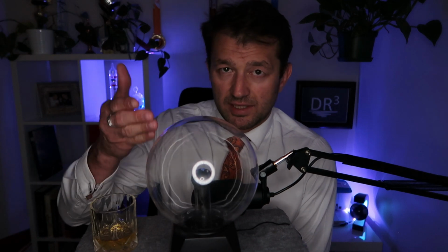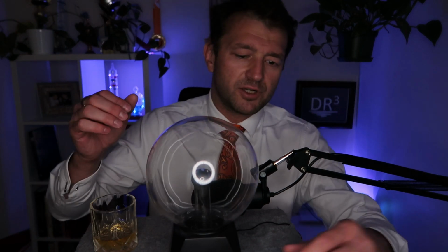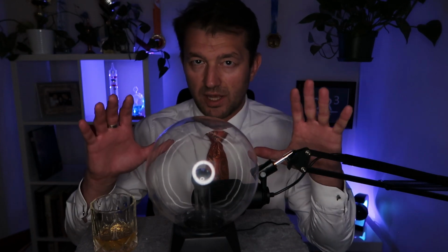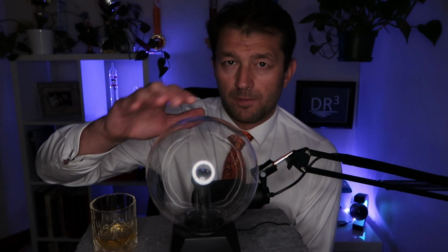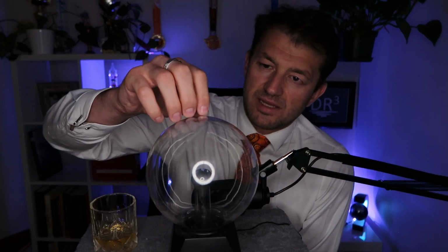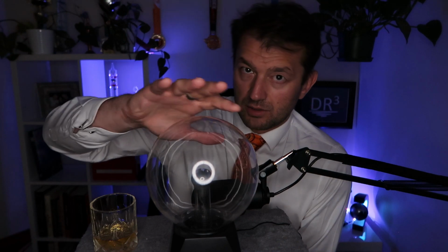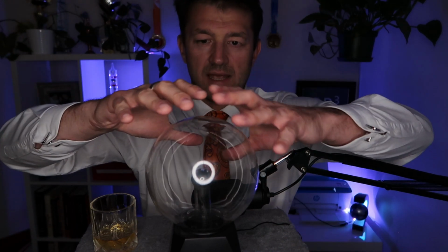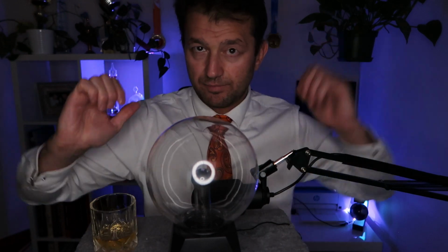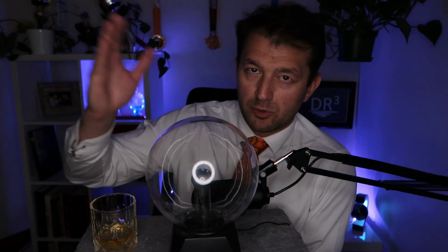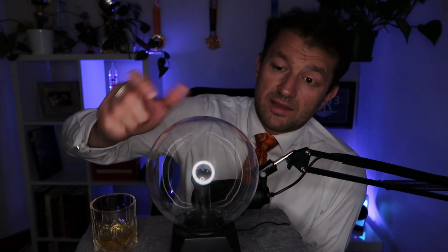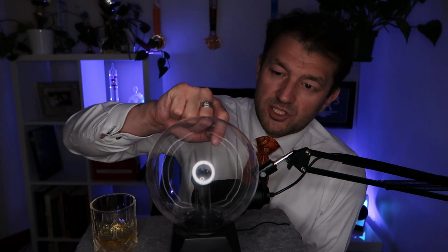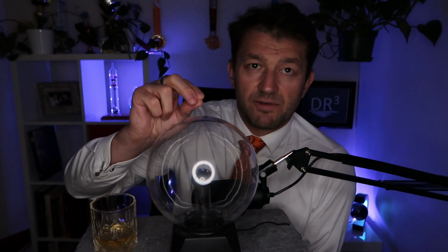As you can see now, it is set up to react to sound, but I will first turn it off completely because I would like to describe the basic parts of this device, and then I will turn it on and explain how it works when the power is supplied. You see, this device has two spheres. There is the outer glass sphere that keeps a mixture of noble gases inside, and these noble gases are mostly neon with a little bit of krypton, xenon, and maybe some other noble gases, helium. And there is an inner sphere, this black smaller sphere, and electrical current is fed through that sphere.